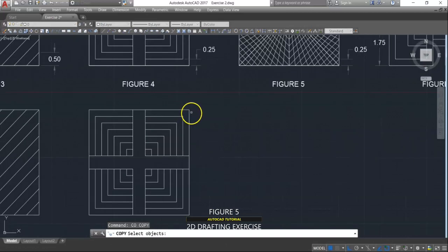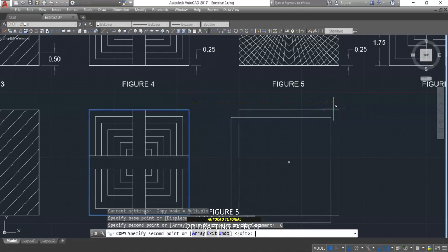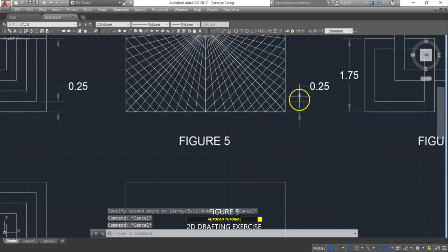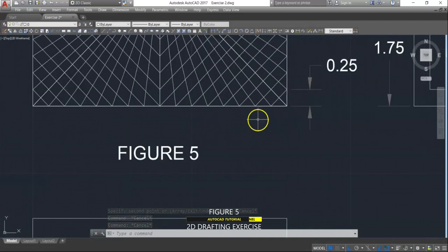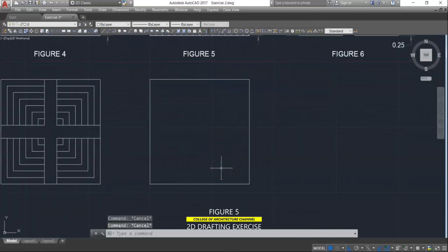And this is a little bit hard for me. And we have a spacing of 0.25 in here. So it means we have 1, 2, 3, 4, 5, 6, 7, 8, a total of 16 spaces in here. So I need to explode this again so I can provide a node in here. When I do divide this into 16 parts, that's the node.